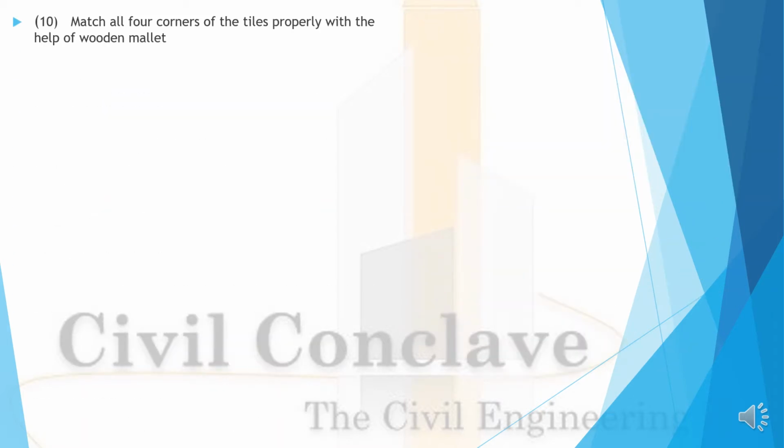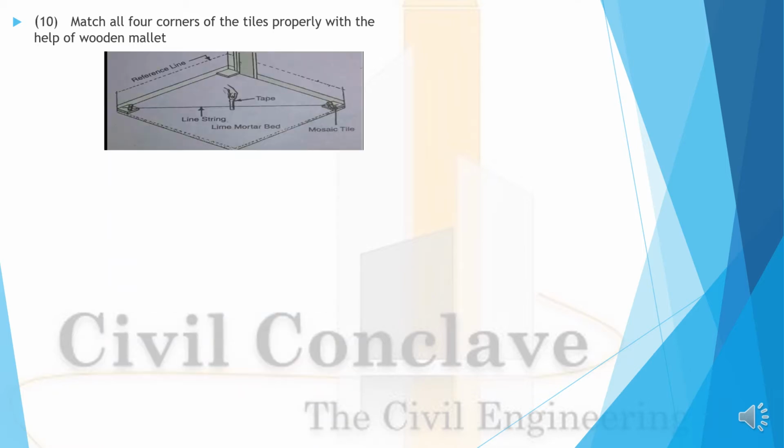The cement slurry is to be used to match all 4 corners of the tiles properly with the help of a wooden mallet. See here, I will show you the things. This is a reference line. A reference line has been given, wooden mallets, okay. This is the way the things have to be done.